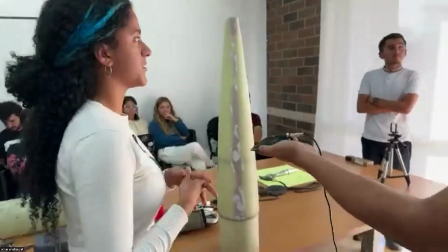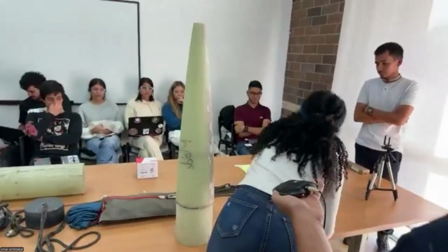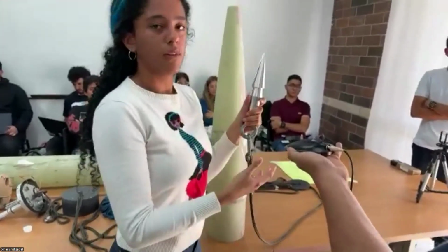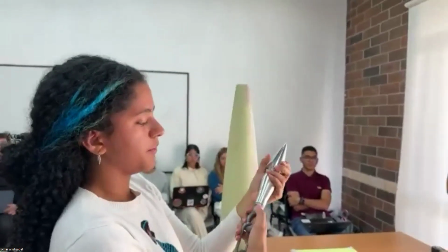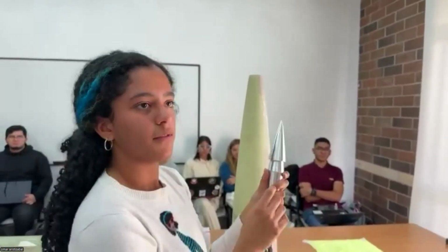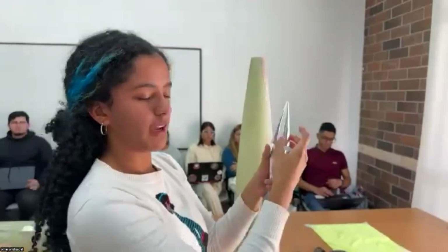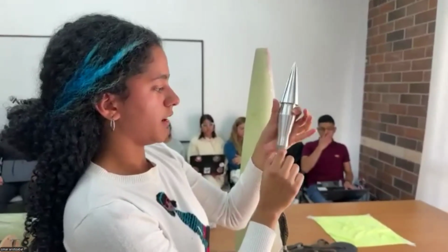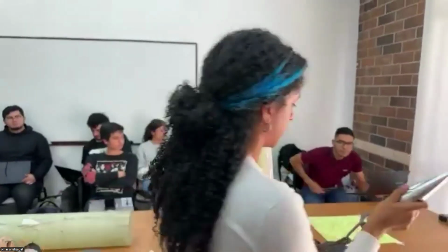Yeah, perfect. I'm sorry. So for the tip we have a metal section. We wanted to have multi-purpose components. Besides being the tip of our nose cone, it is also the point of attachment of the eye bolt for the shock cord. This is threaded, but for the flight it's going to be permanently glued. And for this, we are going to implement a specific system that my peer is going to explain right now.